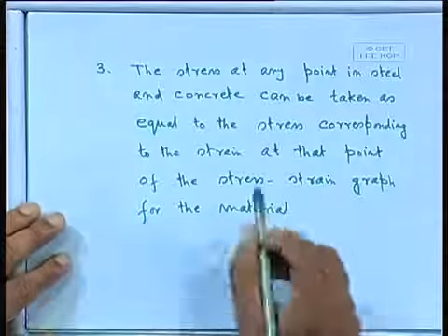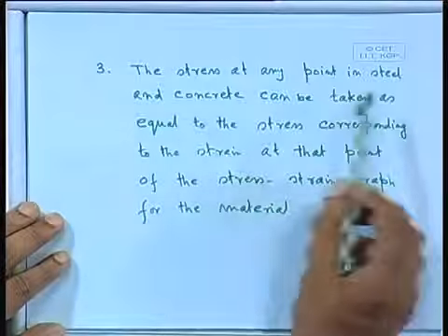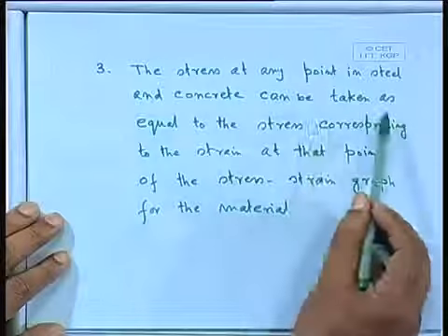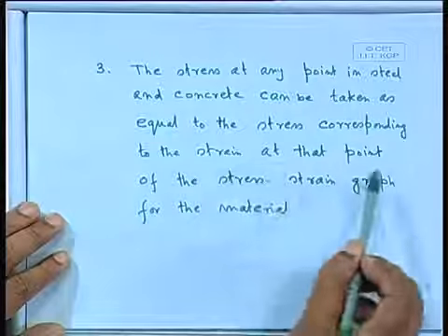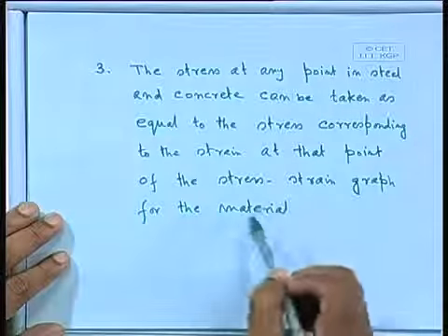I repeat, the stress at any point in steel and concrete can be taken as equal to the stress corresponding to the strain at that point of the stress strain curve for the material.